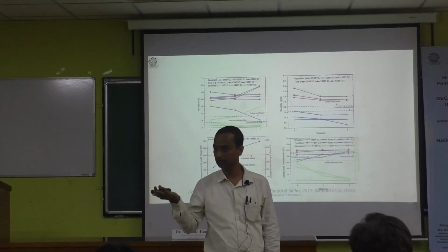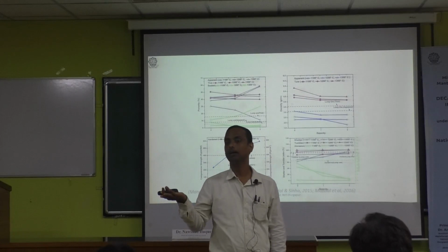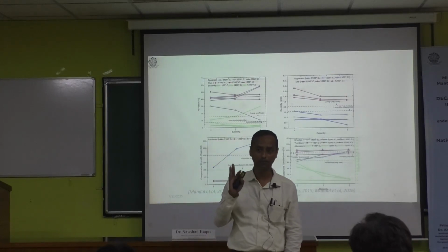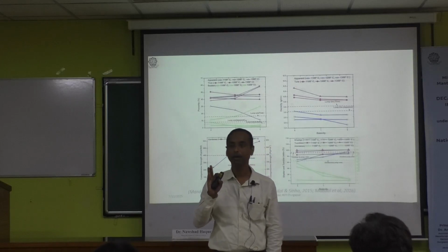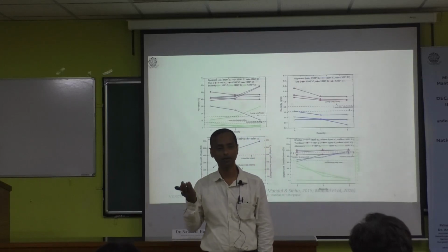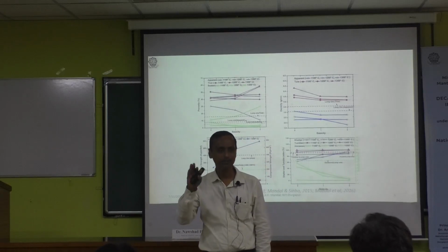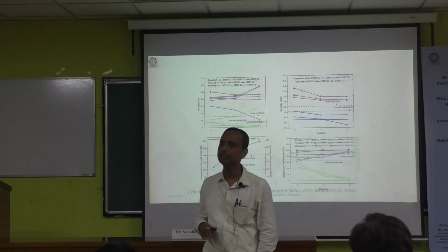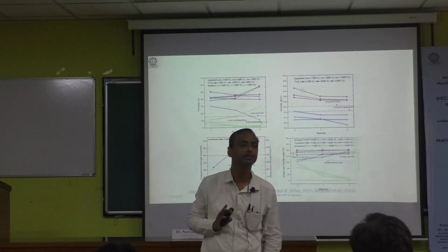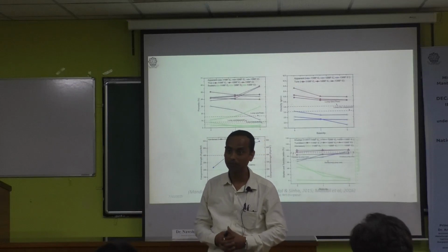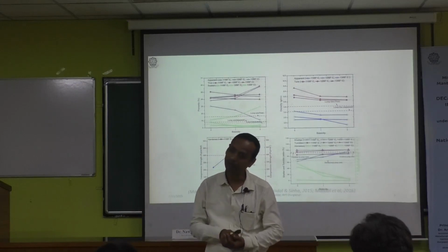It requires hardening. Then what will happen? Drying will not be any problem. But when you go for the hardening of the pellet, at a particular temperature, at 75 degrees centigrade, the dissociation of moisture will take place. Calcium hydroxide bonding will dissociate. Then what will form? Again it will form CaO.